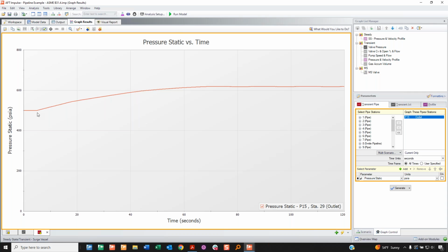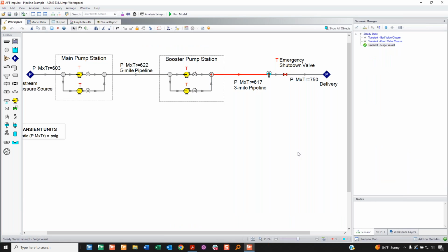It's smooth sailing. You're going to have the check valves closed, pumps are off, everything's protected, and you're way below the minimum. You're barely even above 600. So remember, our case design pressure is 700. Okay, and again, we could look at the multi-scenario graph with that case going on, but I think you get the idea. There's so many other mitigation methods we could go through.